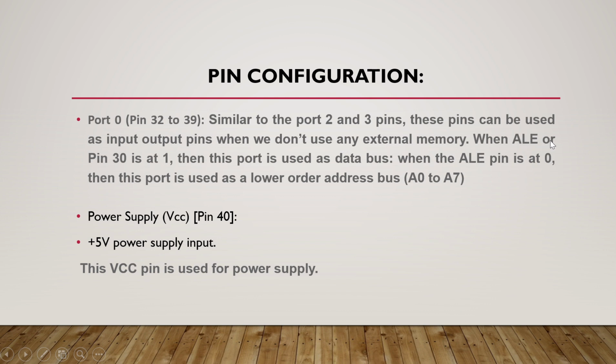When ALE, or pin 30, is at logic 1, this port is used as a data bus.